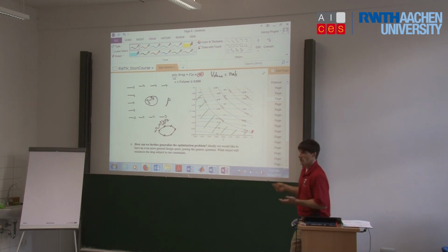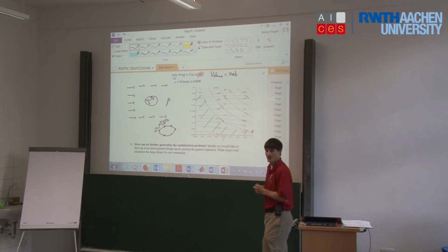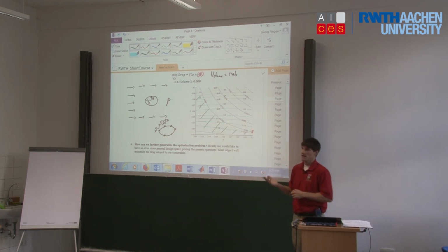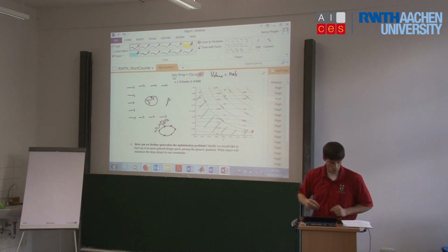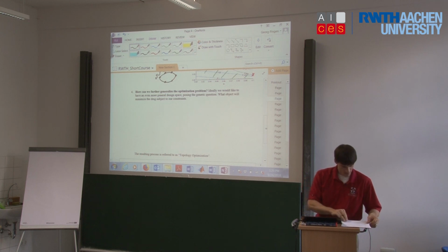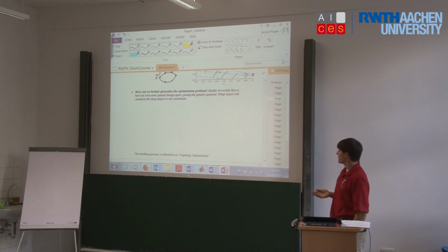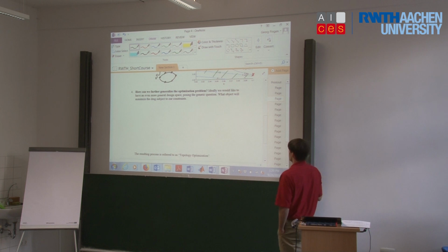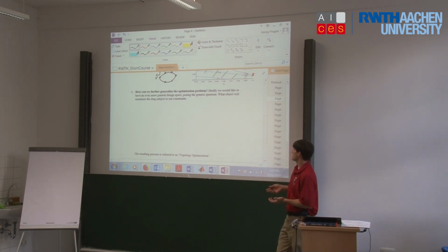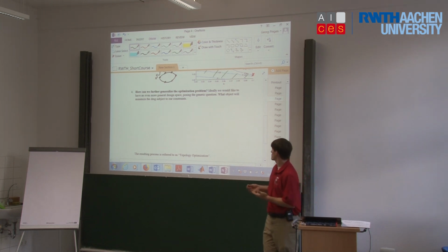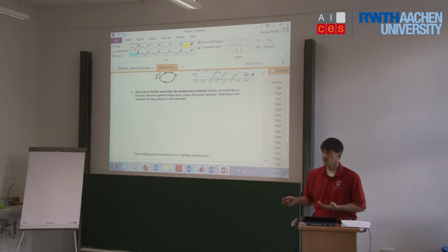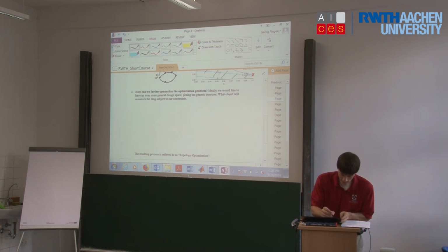The problem with that is that we can't plot it and look at it nicely. And so for now, we'll look at these two design variables, and will later become more general when we look at topology optimization. So now the next question is, how can we further generalize the optimization problem? We would like to have an even more general design space, posing the generic question: what object will minimize the drag subject to our constraints? Okay, so what object?